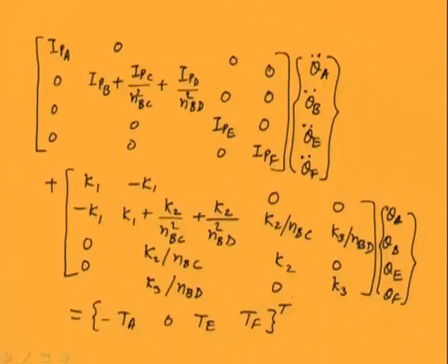Now after assembly, the equation will take the following form. Now here you can see that we have 4 displacements, that is at nodes A, B, E, D only. Now we can apply the boundary condition here, and especially you can see that this particular term of the torque gets cancelled totally, because when we assemble the matrices, those torques cancel each other.